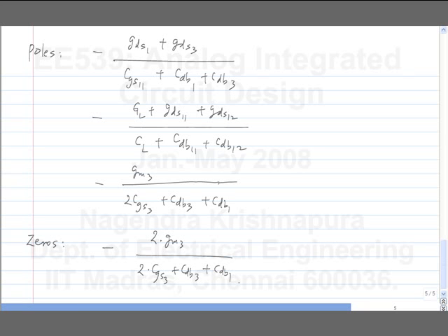So now, what is the problem? Is there a problem, or can we just use the op-amp as it is? Yeah, that's correct. We have to ensure that there is 20 dB per decade roll off. Now, the problem here is that P1 and P2 can be close to each other. Okay, relatively. Now, that depends on the relative values of GL and also the value of CL. Okay, the conductance here is larger, but also there can be a large load capacitance. So, it is quite possible that P1 and P2 are close to each other. So, will we have 20 dB per decade roll off in that case? No. Okay.